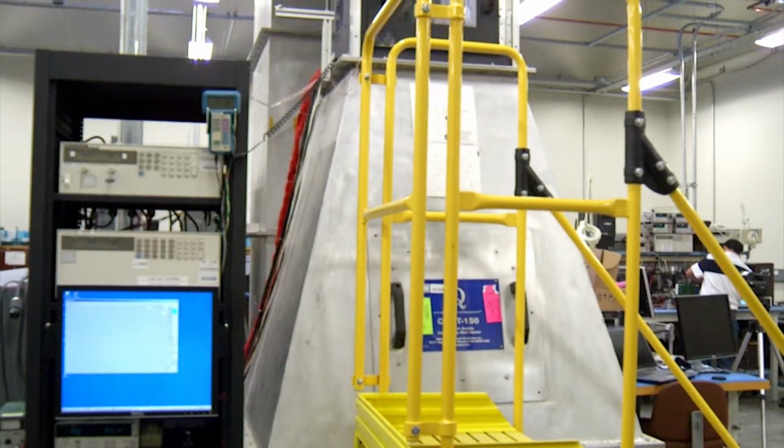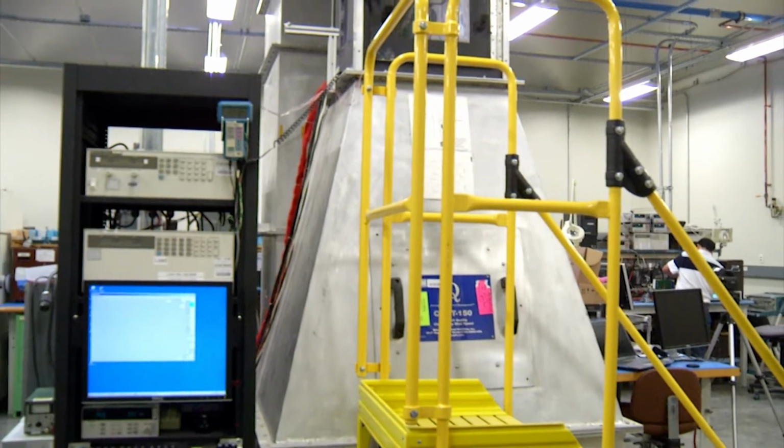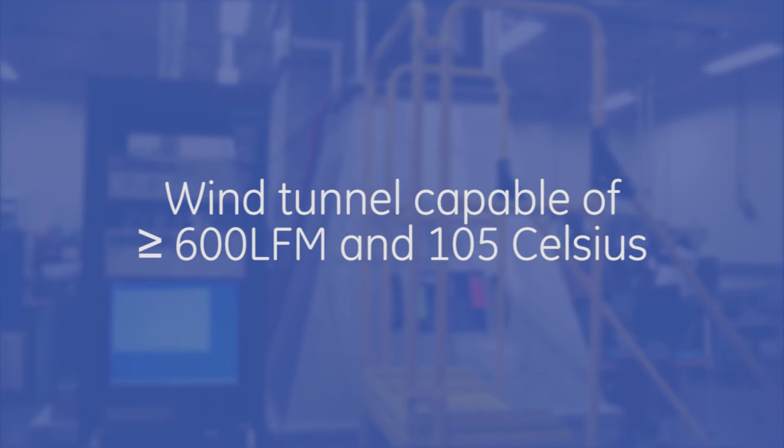As described earlier, derating curves are generated by plotting operating points at particular airflows and ambient temperatures across the entire operating range of the converter. Therefore, these tests must be performed in a wind tunnel, which is capable of accurately providing uniformly heated airflow up to 600 LFM or greater and up to 105 degrees C ambient temperatures.